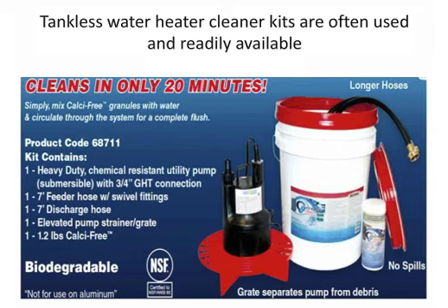The good news is for those cleanings, the kits are fairly available and they're not badly priced. Tankless water heaters, that's a very popular item these days, and most all of them tell you, as a contractor or a homeowner, you have to go out there and descale or delime them. So there's a lot of kits out there. It's kind of a nice little one. That's the self-priming pump. Looks like a little sump pump. It's on a stand. Comes in a bucket with a screw-down lid, as you can see. Comes with some washing machine hoses, so it's kind of all together right there.